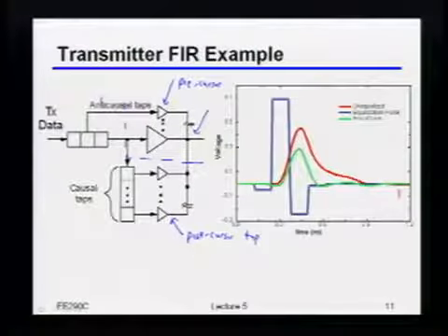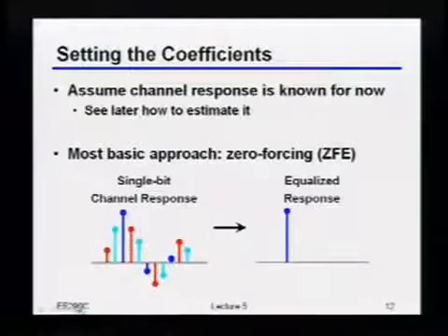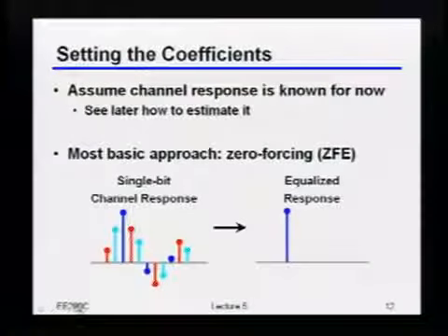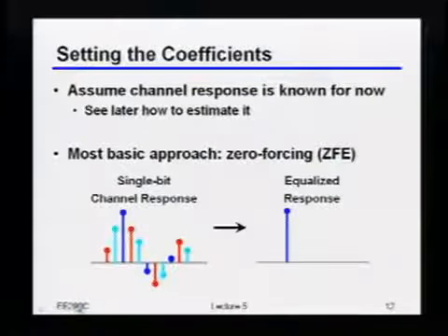Okay, so now's where we come into one of the other questions about what type of equalizer this is. In particular, to get there, it's useful to walk through how you would actually set the coefficients for some equalizer like this. Because as I said, the whole reason we went to this FIR is that it is a lot more flexible. But unfortunately, it being a lot more flexible also means it's a lot more of a pain in the butt to figure out what the right thing to do there actually is.